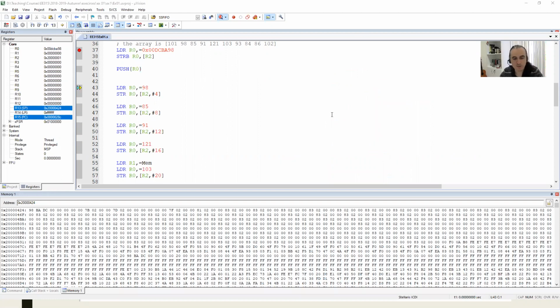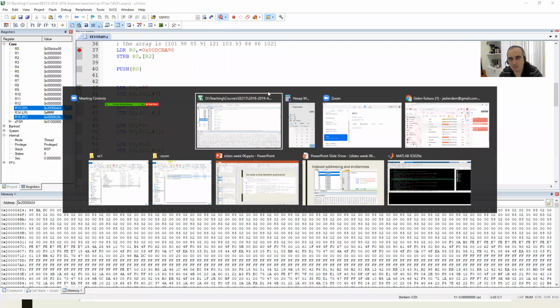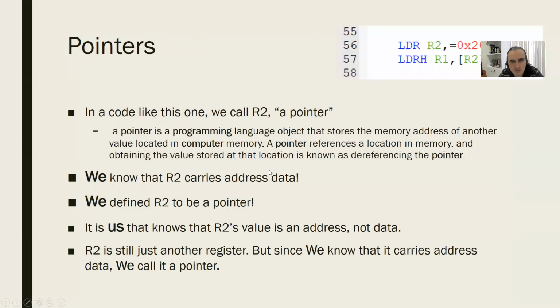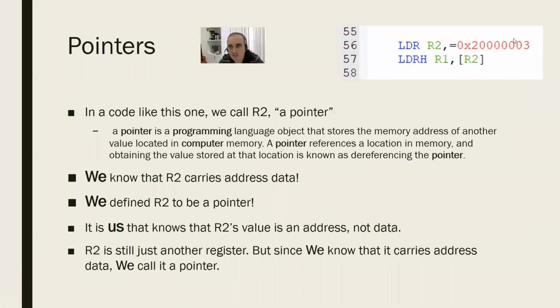Okay, now I've been talking about this pointing to memory. So stack pointer is pointing to memory. R2 is pointing to memory. So guys, actually, if you need to write something to the memory, you need pointers. These are called pointers, just like in this example. In order to write to memory, you are using index addressing or stack pointer. So you need the address of the memory to be written to a register. These registers used in these index modes, or the stack pointer itself, are called pointers.